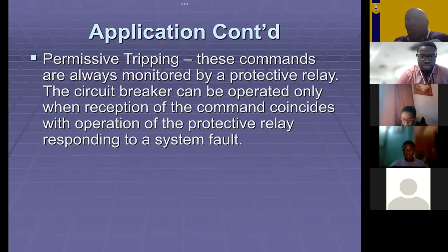Remember, we gave two permissive schemes: the permissive underreach and the permissive overreach. It was just which one of the instantaneous zone settings was used to send the signal.